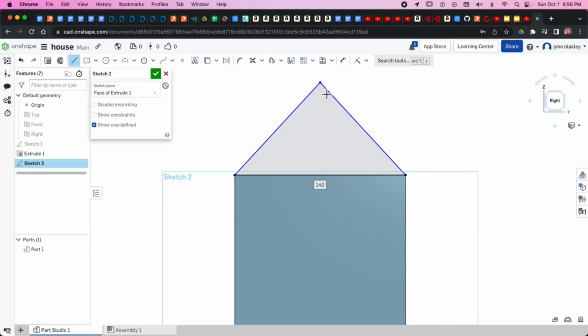and let's make another constraint. But let's use a construction line now. A construction line is like a hidden line that you can use to plan things out without it being final. So construction line, let's click here. Let's make sure it's straight and then connect it to that. And then I still want to press escape to break out of that.